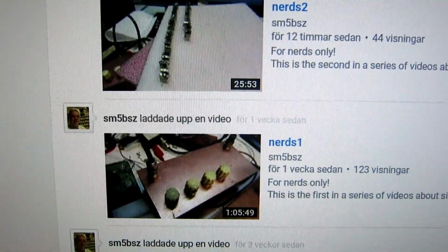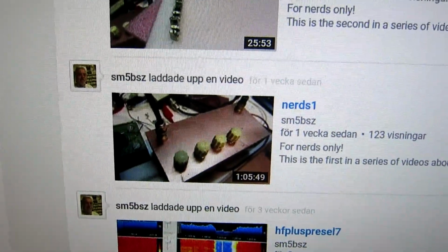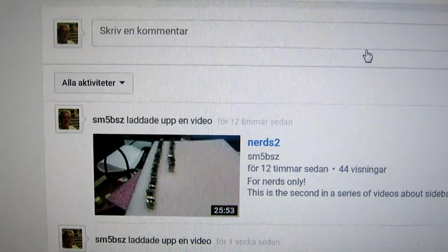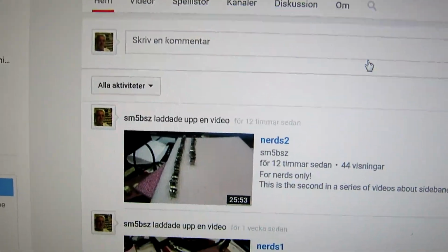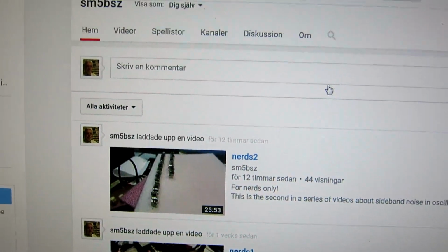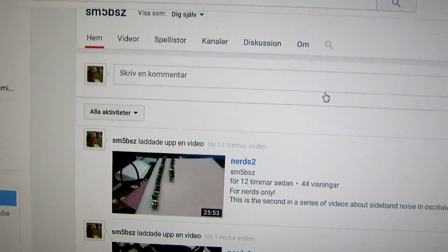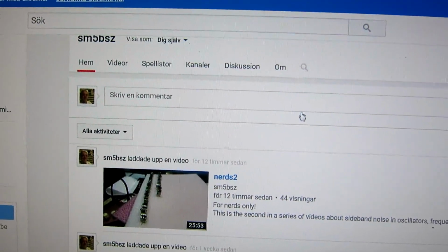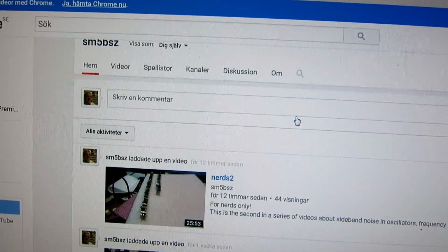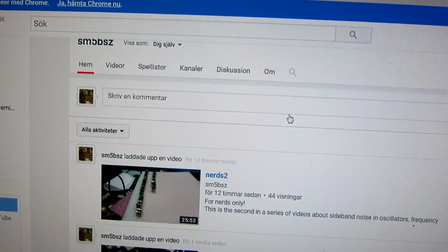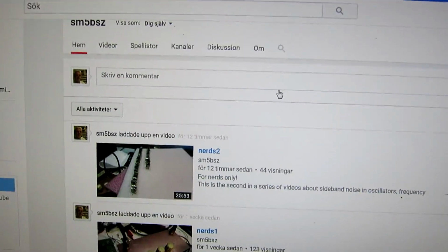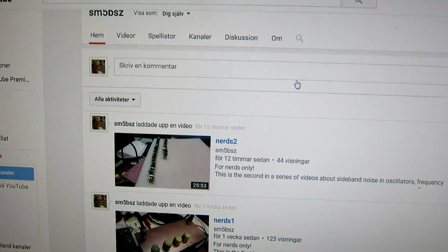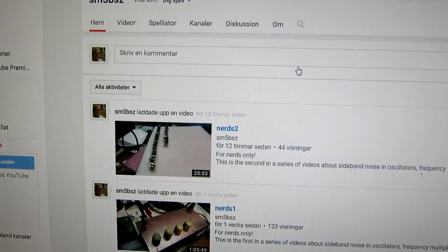The results from the experiments in the previous videos of this series, this one and this one, is that the limitation in my experiments is due to noise in the crystals of the notch filter. The notch filter operates at about 10 times higher power than the crystals in the oscillator. So 10 times more crystals would be needed if operated at the same impedance.